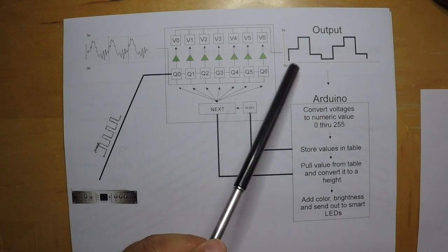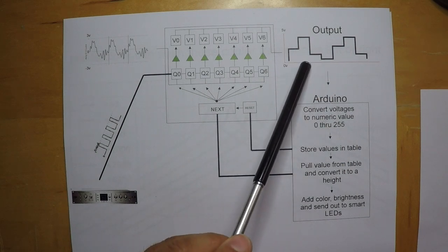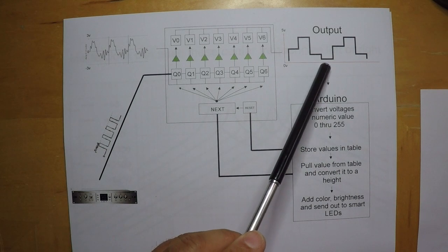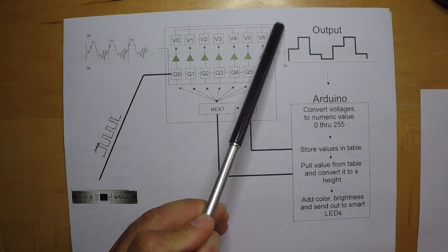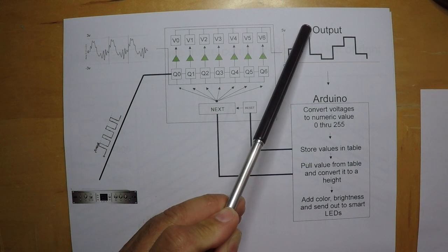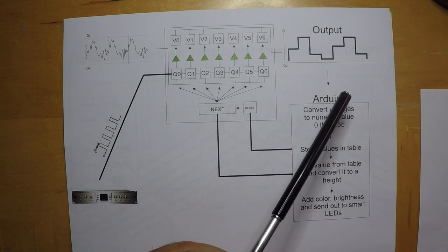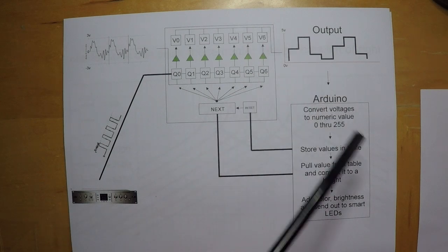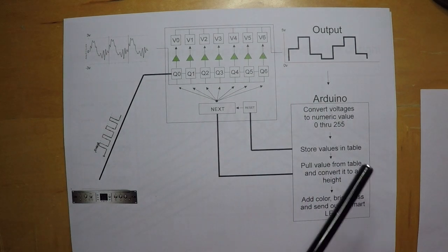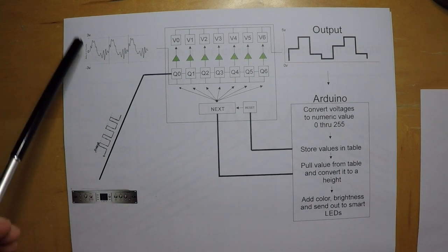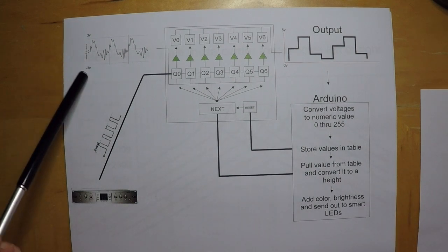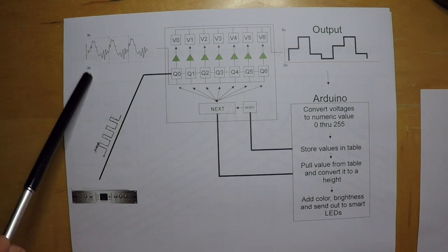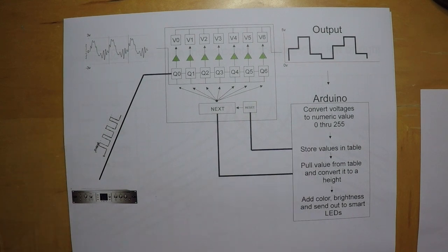It'll map 0 volts to binary 0, and it'll map the maximum voltage to binary 255. So Arduino has some tools to work with ones and zeros, because that's what Arduino likes to work with. Arduino definitely doesn't want to deal with negative voltages. In fact, if you feed negative voltages to some of the pins on Arduino, you're pretty certain to hurt the Arduino.